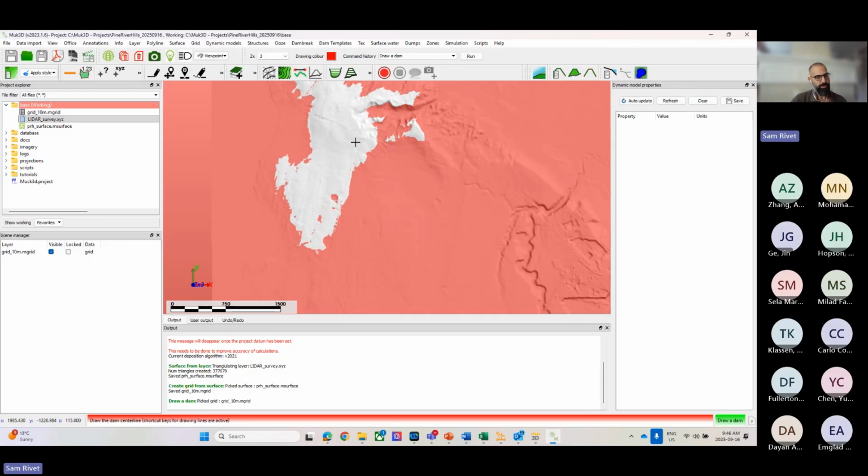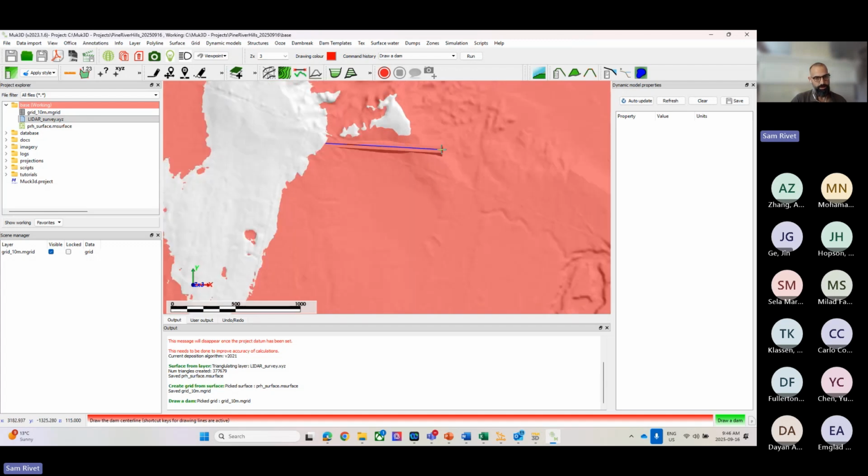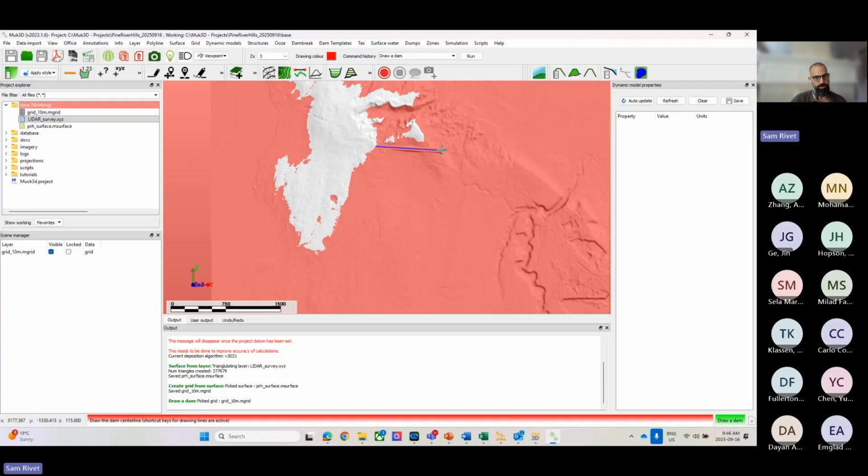So I'm going to start by placing my dam in this area. So I'm going to start by placing a point inside this piece here. So click once here. And extend this out. You can kind of see the makings of my dam shell if I zoom in. Put a point here. I'm going to put a point here, here, here. I'm going to put another point here to seal it against that topography, even though we can't see it. And then because in the future, this dam might very well go above this piece of topography, so I do want to close this dam, I'm going to hit C to finish it off so that it's closed. Then spacebar when I'm done.